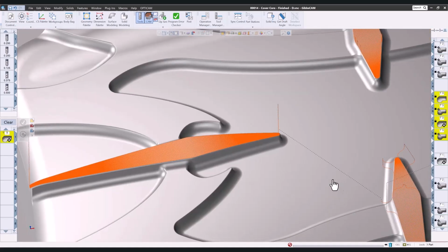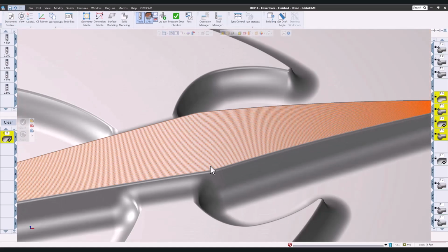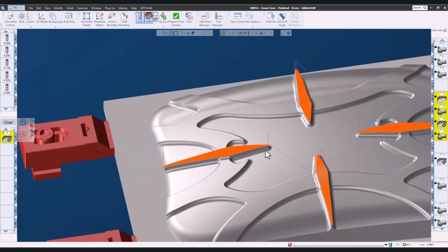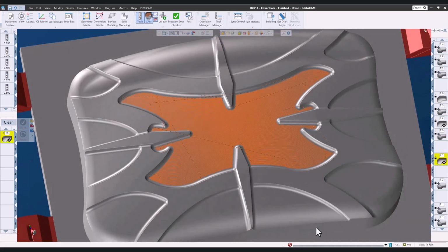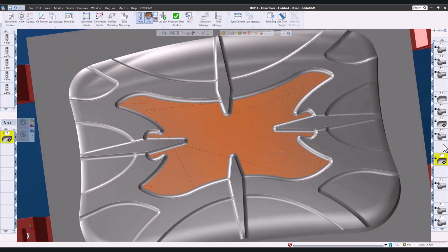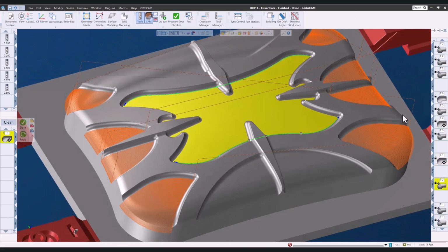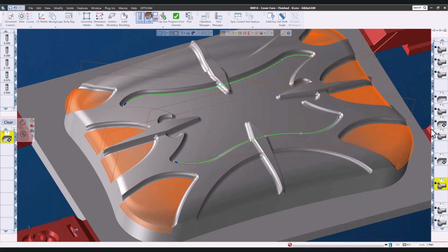But they all start with one shape at one edge and morph as they move across the surface to the other edge. For this center section, I went back with the advanced 3D in-curve flow using that modified geometry. And then for the 8 pockets on the ends, I used the parallel to curve from the multi-axis toolpath based on surfaces toolpaths.